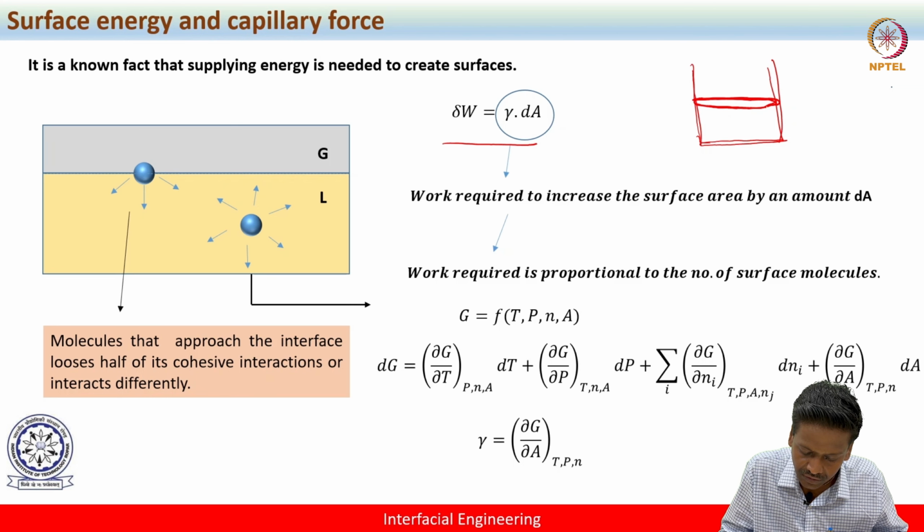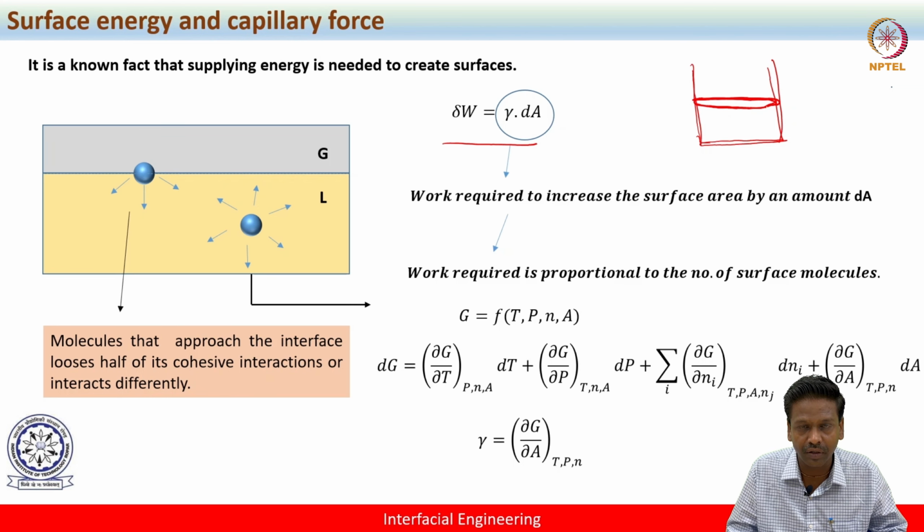Now, this wire is very tiny and very light in weight. So you know that there is surface tension acting along this thin wire at the interface. Eventually, what happens is that because the water molecules try to maximize their contact area, there will be a net imbalance in the force. There will be a force in the downward direction. So this surface tension will pull this wire downward, right, in this way.